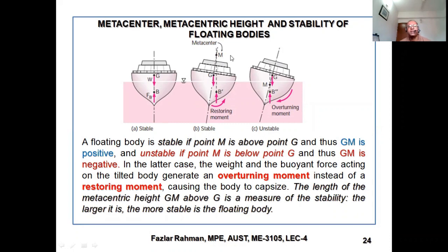Then they know where the CG of the empty boat is, with all the equipment. Then they use special software, and they get a higher salary, you know. They distribute all the containers by software to make sure that they keep this metacentric height as big as possible, to get the restoring moment. That is the application. They put in a container, then run the software, and see what the condition of the ship is, the restoring moment, to keep the CG at a certain level.